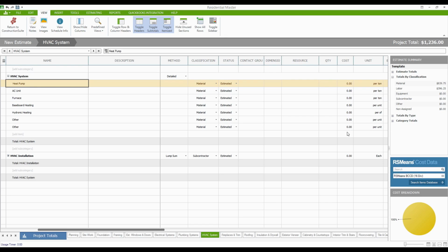Dimensions and quantities are going to be tied together in most cases. The dimension would be a measurement that you're doing, so you might go in there and measure the dimensions of the master bedroom. And those dimensions could apply as you're setting up things like carpeting for the bedroom or hardwood floors in there. The flooring dimensions would determine the flooring for the job itself. If you do the measurements for the walls, total square footage of interior walls, that goes back into the installation for the assembly that we were talking about earlier. You could plug that in as part of that. But ultimately, the dimension determines what the quantity is for most of these items.